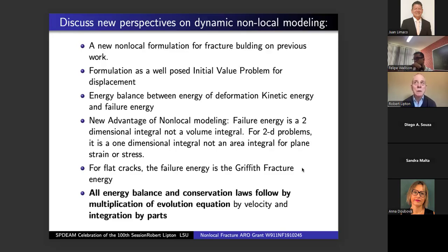Now, going into it, we do not assume that a fracture is one-dimensional. We don't even assume a fracture. We just assume some sort of damage, and then it evolves into a fracture. Or if damage occurs, it may not even occur. You just may have a linear elastic material in an initial boundary value problem, and you just see elasticity, linear elasticity. On the other hand, if the specimen is loaded such that drastic loads are applied, you may then see the emergence of a crack as part of the dynamics.